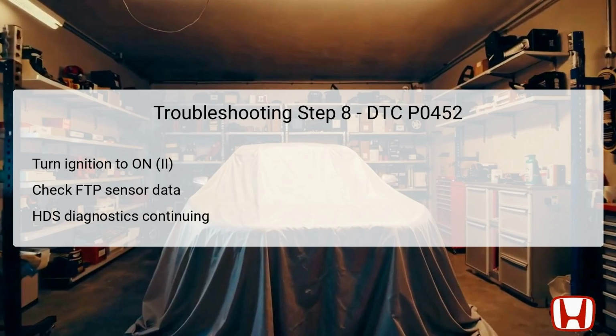This check will help to assert whether the absence of the sensor contributes to a significant change in reading. Should these values appear again as previously noted, further steps must be taken to investigate the integrity of the wiring and connections leading to the ECM.